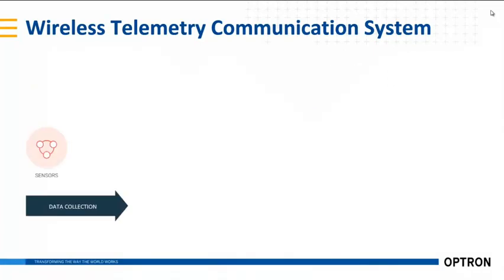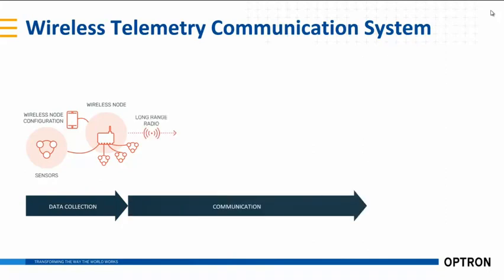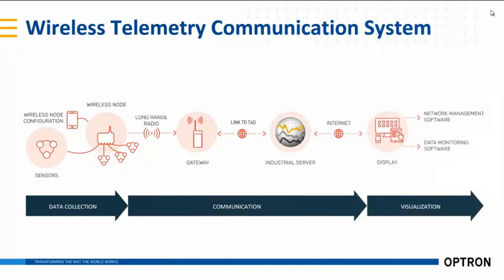So how it works is you've got the sensor, which is your geotechnical sensor, wired in locally to a data logger. It's configured once on site or in the office prior to installation. It's configured to communicate with a single gateway using low frequency radio waves, which are certified to work in South Africa. So there's no licensing issues there. The gateway is linked directly into T4D, and our guest speaker, Christian, will describe T4D in a bit more detail, where any users can then interrogate the data, do analysis and reporting, alarming, etc.